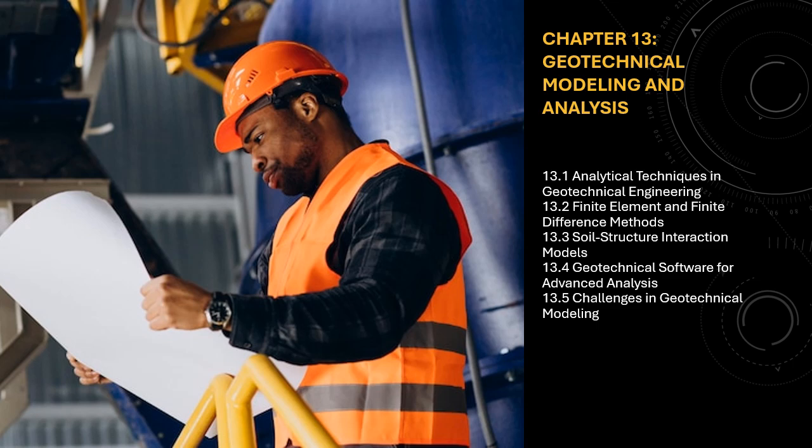13.3.3.1 Seismic soil structure interaction. In seismic loading, the soil's ability to absorb and transmit seismic waves plays a crucial role in determining the structural response. The dynamic interaction between the structure and the soil can influence the overall seismic response, including effects like resonance, soil liquefaction, and foundation amplification.